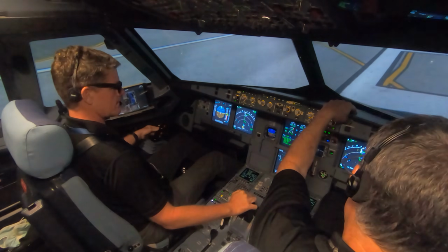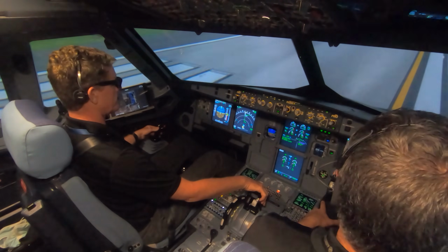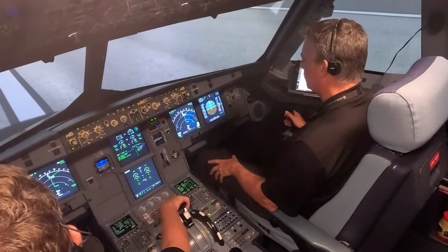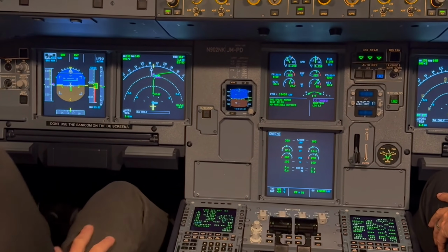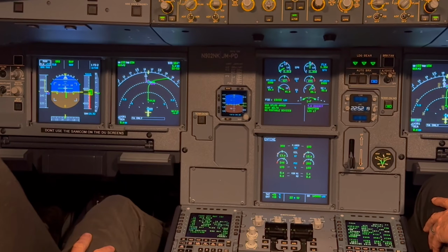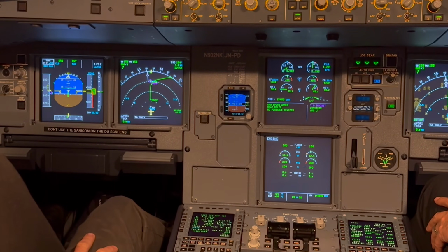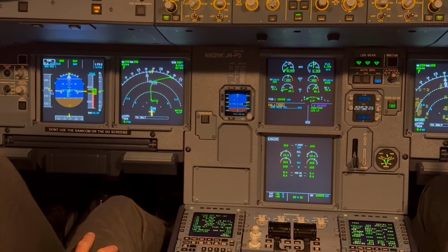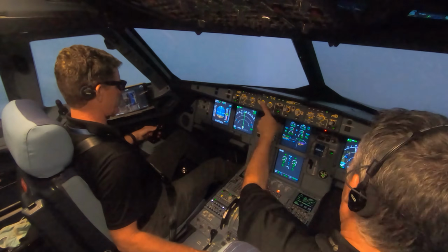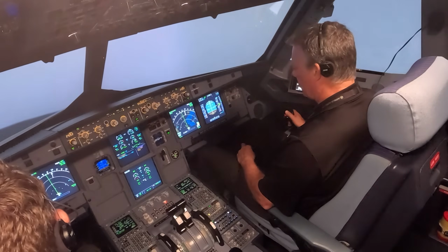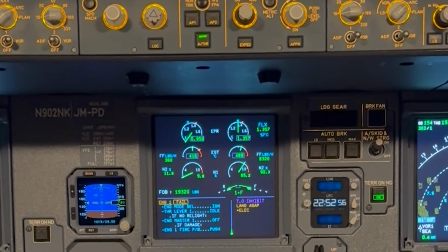For brevity purposes, we'll go ahead and fast forward the first part of this demonstration since it's identical to having an engine failure with damage. V1, rotate. Notice with this engine failure, EPR decreases without any other symptoms of engine damage, like we discussed previously. Positive rate. Bring us forward to the beginning of ECAM actions. Pay particular attention at the point in time the crew decides to complete the engine relight, once there's been a determination that the engine flameout did not involve any damage.